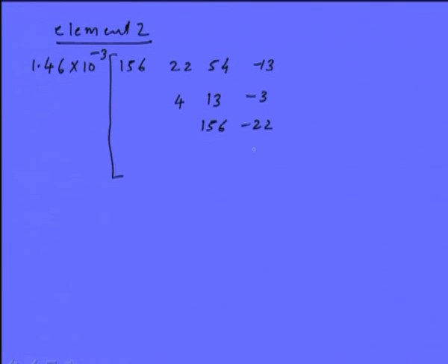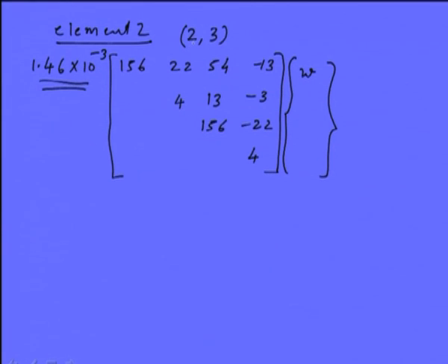If there is a step change in the diameter of the shaft, then we may have changes, especially in these terms, because they contain the dimensions of the shaft. Here again we have some changes, because now element 2 contains node 2 and node 3 on the left and right side of the element. So we have W2, W2 prime, W3, W3 prime, and these are accelerations, so double dot terms will be there.